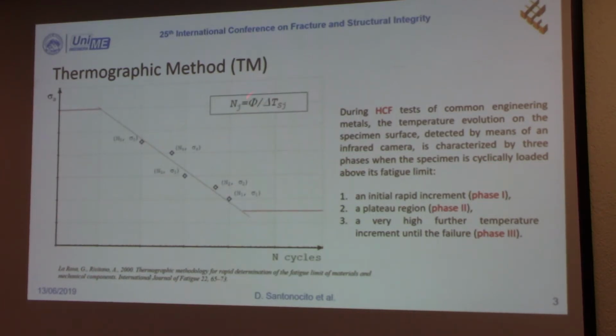Another improvement, we can plot the S-N curve of the material, because as we previously said, phi is a constant of the material. So knowing the stabilization temperature, I can easily retrieve the number of cycles at which the specimen will break at that stress level.